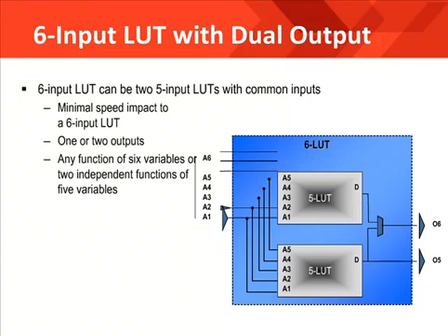Also keep in mind that if you're trying to design to the maximum speed quoted in the device datasheet, you have to remember to limit all of your delay paths to 1 LUT or 1 logic level. This is not typical, but some customers do it by extensively using pipelining and by minimizing their combinatorial logic. The Designing for Performance course discusses pipelining.